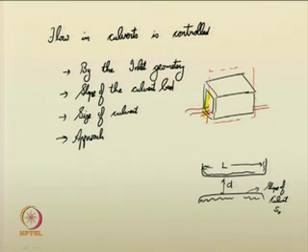This is the inlet condition or the approach condition, and the outlet or tailwater conditions. So, those things are also important, approach and tailwater conditions. They also play a significant role in determining how the flow is occurring in the culvert.